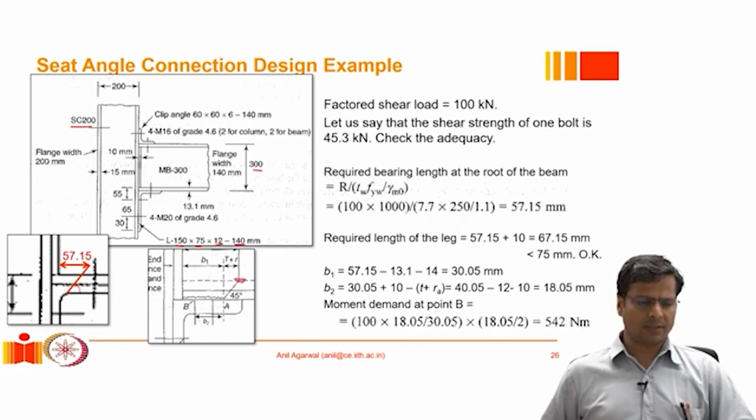So, right, this is the cross section. This should be the critical cross section above the radius of the fillet. That's where the crippling failure could occur. So we should look at this cross section, and generally we assume that if the stress is acting over this length at the bearing surface, as we go up, the area over which the stresses are distributed will be spreading out at an angle of 45 degrees. This is the general assumption we can make that is used for steel structures.